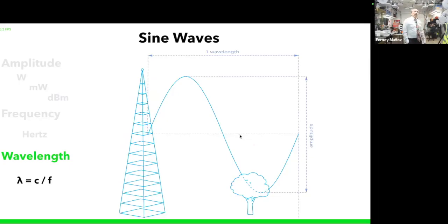If we are doing the math, let's say we have an AM radio station, we don't have very many of those left, but let's say I'm in Salt Lake City and you have a station transmitting 50,000 watts in the dial, let's say it's in the 1,000. These transmissions are tuned in kilohertz. So 1,000 times 1,000 is going to give you 1 million hertz, meaning a transmission that is sending waves at 1 million cycles per second.